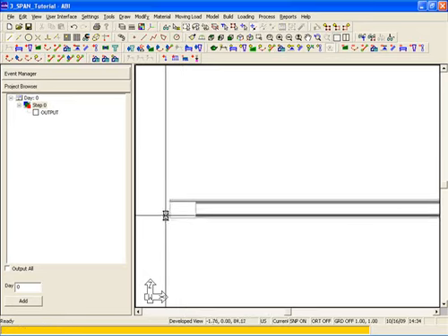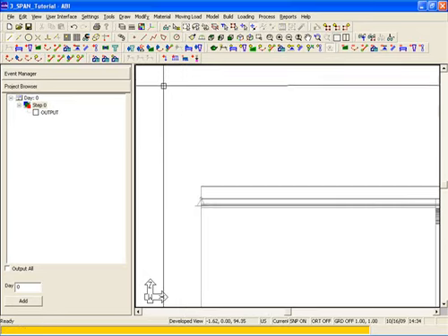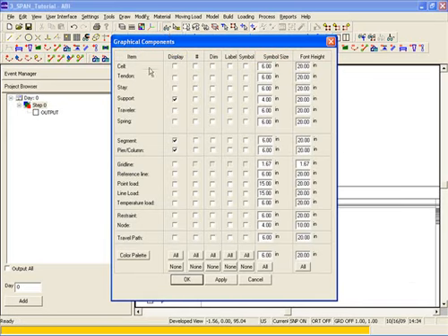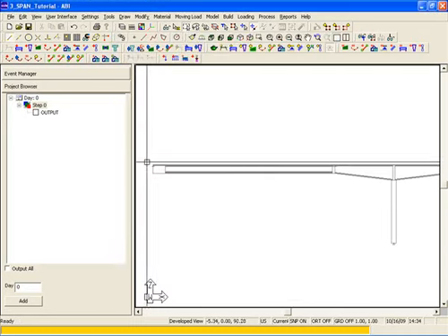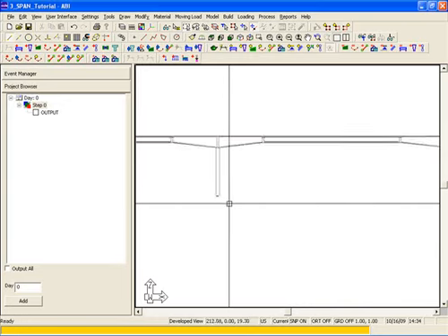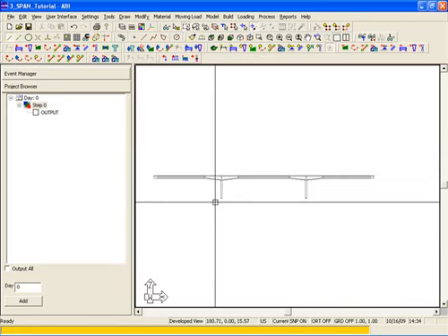To change the symbolic size of the supports, we can go to Select Set View Items, and at Supports, we're going to go ahead and change the symbol size to 15 inches. That allows us to grab the supports easier when we go to modify and when we go to install them.